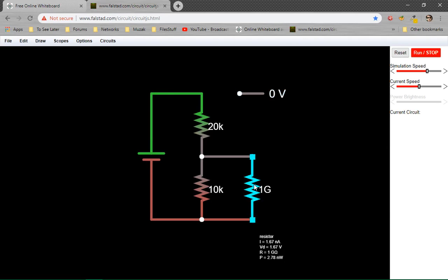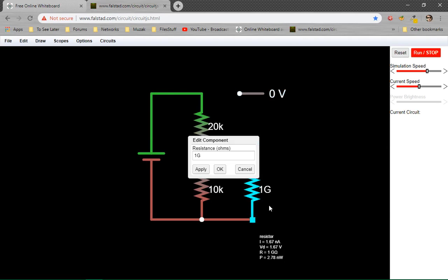As you can see, if you go to the resistor, the big one, you can see how many amperes, or intensity, is going through it, and this is really low. 1 nanoampere might very well be lower than the noise picked up by the circuit from radio frequencies and static electricity. So for any practical purposes like turning on a lamp or sensing a signal in electronics, this is useless.